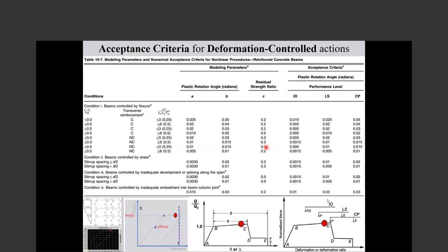We have lots of solutions in the literature, from very well established solutions to include the higher mode effects, the classic work of Chopra and Goel for modal pushover, to the consecutive pushover, which seems to be one of the best for taller buildings, and exactly around the same mass ratio that you mentioned is used as a threshold.